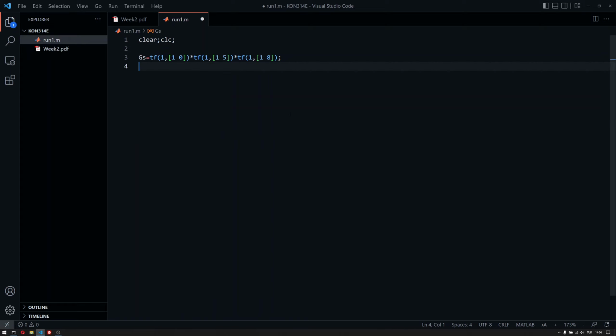So even though we have a third order system, we actually know that, for example, a first order system that looks like this, a very basic one, 1 divided by s plus 1, has 4 seconds of settling time. We know that for a fact, since we can use the inverse Laplace transform and apply it to this. So let's assume that we have